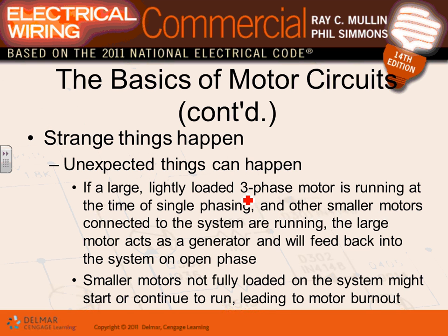This is talking about strange things happen. I'll show you guys in a second. If you have a single phase in your system and you have a big fat motor running here, you know what happens with that big fat motor, guys? It can generate a third phase that can start other single phase motors. So it backfeeds, like creating another phase if it's lightly loaded. So if you're in a plant,